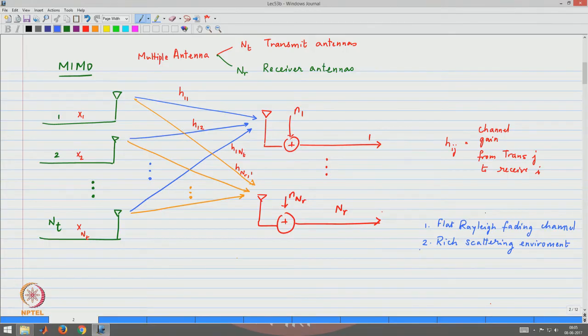We also have not specifically introduced it, but it is important for us to recognize that the spatial parameter, the one that gives us the advantage of the channels, can be indicated as N, which is the minimum of the number of transmit antennas and number of receive antennas. That is an important indication of how much benefit we can achieve from such a system.